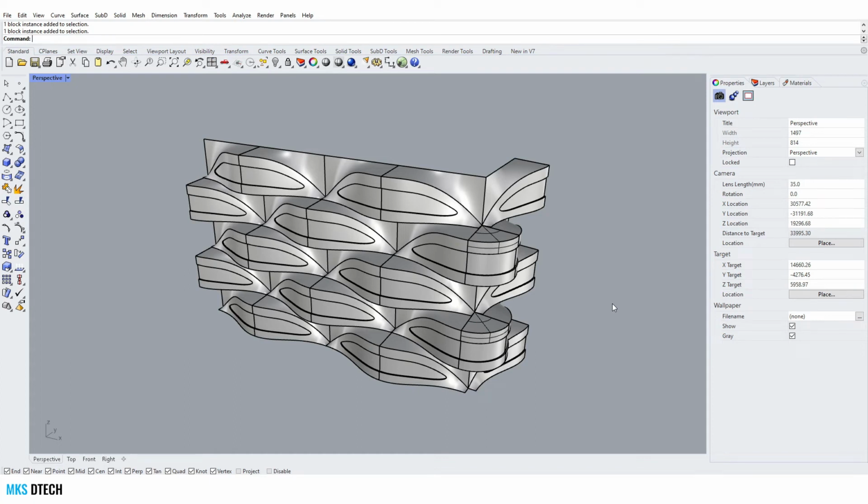Today we're going to look at how we can create Rhino blocks and export them into Revit as families, because Rhino blocks are always considered families. We'll also have a look at how we can assign specific properties and parameters using BEAM, and then update our geometry in Revit in case the design changes.